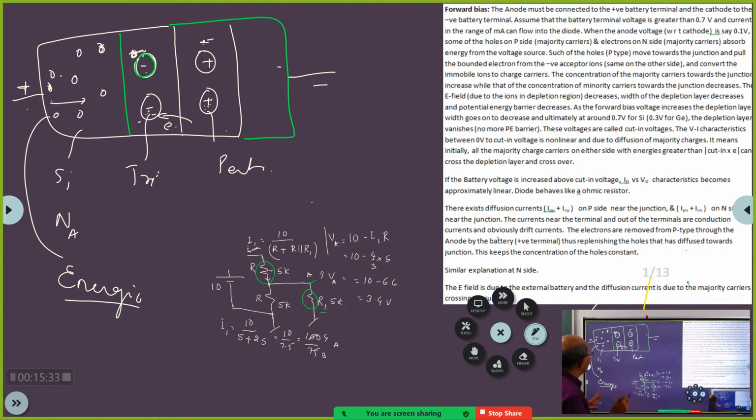So these were immobile charge carriers. Why were they immobile charge carriers? Because this had a trapped electron here. That electron was trapped. That is why I am showing it by a minus sign. Now, when a highly energized hole comes near, this electron is pulled by this hole. And therefore, this, which was hitherto an immobile charge carrier, now has become a mobile charge carrier. Got it? And when you knock off the immobile charge carriers like this and make them mobile, then this depletion layer will reduce in its size. Got it?